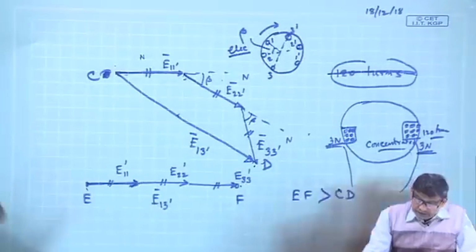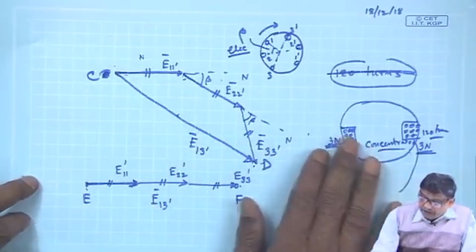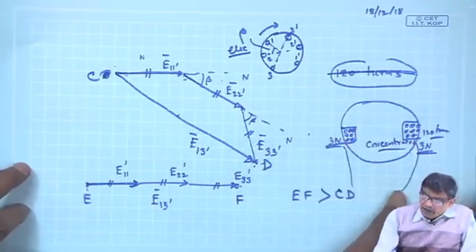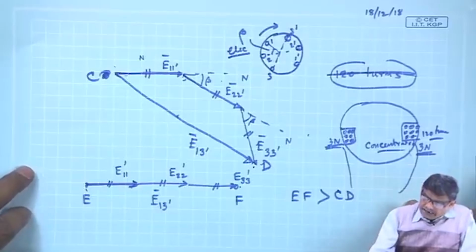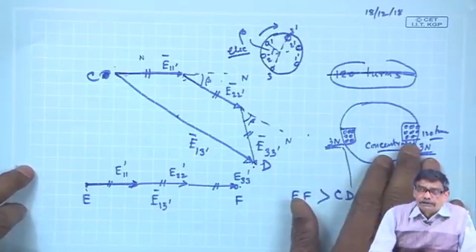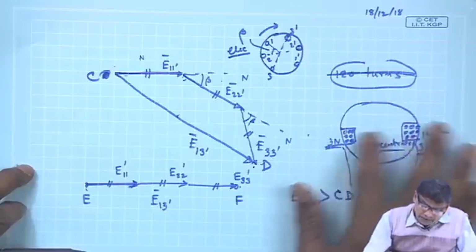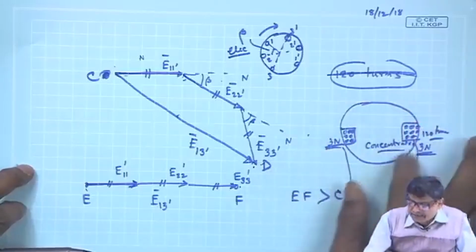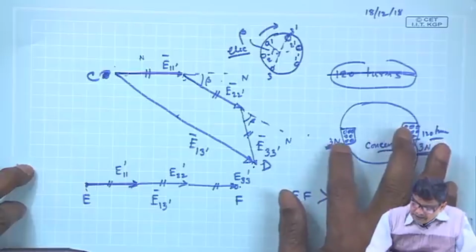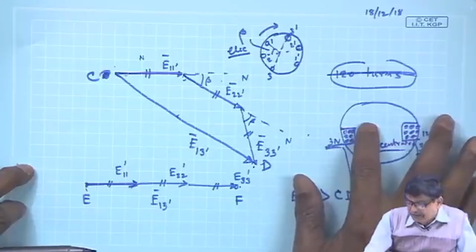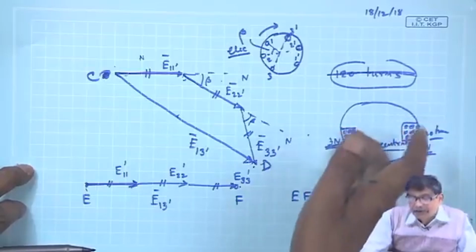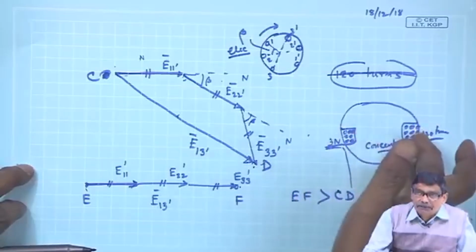Achha. Now, coming back to where I left in the last class, that coils will be distributed or concentrated. Concentrated, for many reasons, is not wanted. If you accommodate so many turns in a pair of slots, the rest of the place remains unutilized, and also there are restrictions on how many conductors you can put in a particular slot.